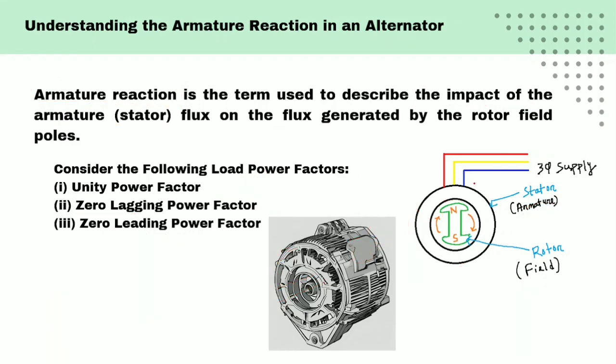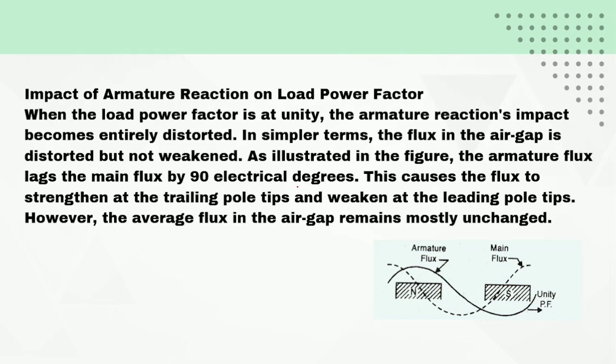In detail we will discuss unity power factor, zero lagging and zero leading power factor. First is unity power factor, UPF. In this diagram, the solid line is the armature flux and the dotted line is the main field flux. The effect of armature flux on the main flux is called the armature reaction.